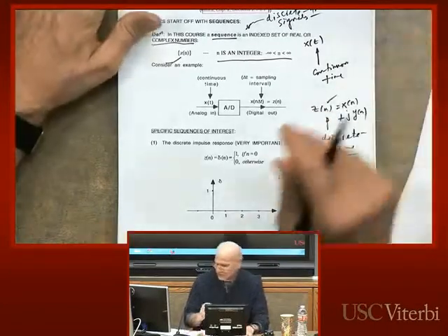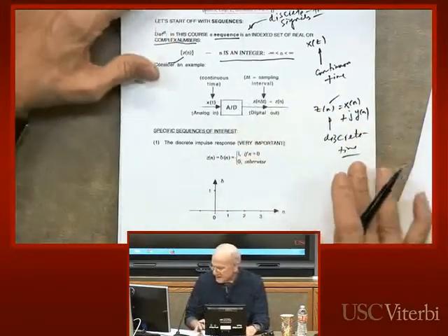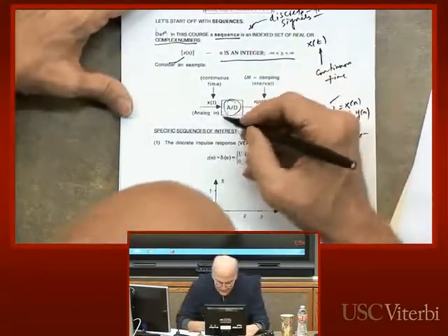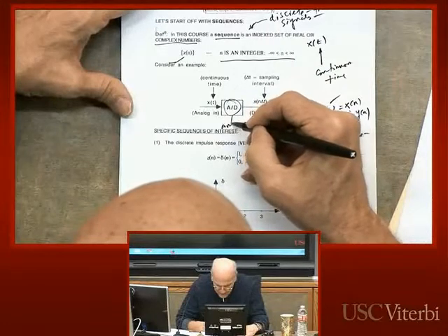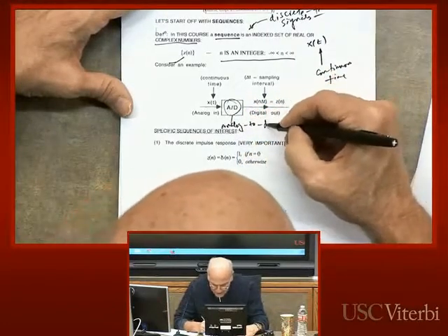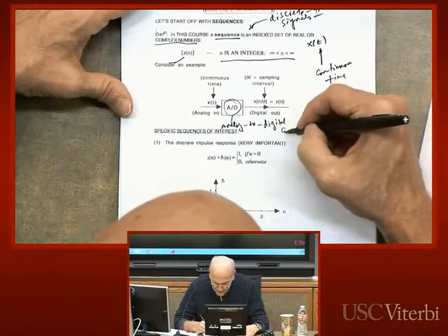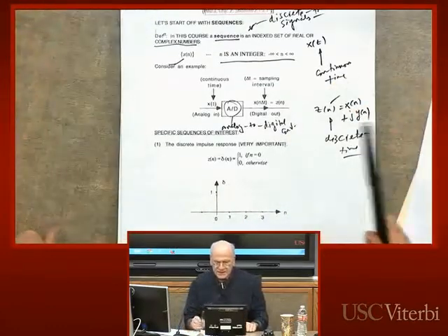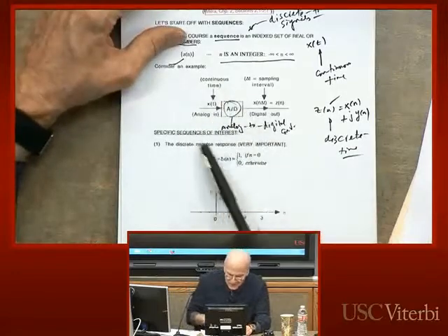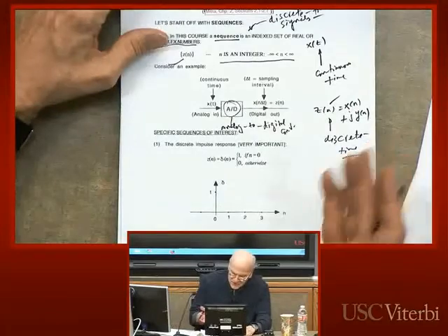In an actual hardware system, they also might be stored in memory in a computer, but they might be coming from something we call an A to D converter. A to D is an analog to digital converter. So that's another perfectly valid place these signals could be coming from. In this case, it would be a mix of both worlds, both the continuous time, where you might have a signal x of t going in, and the discrete time.